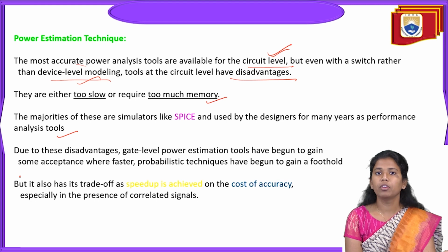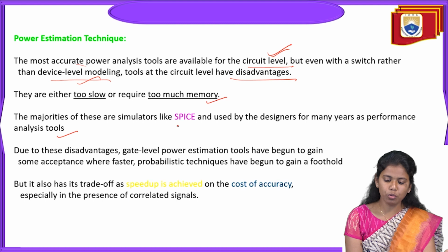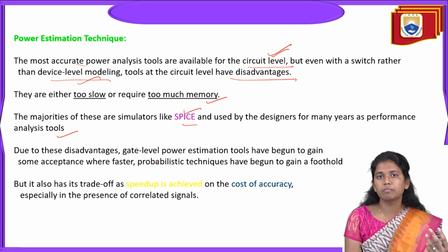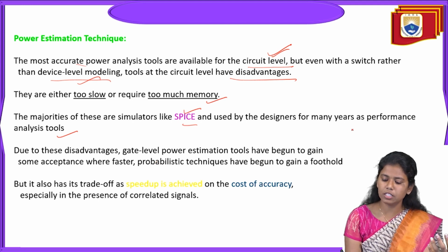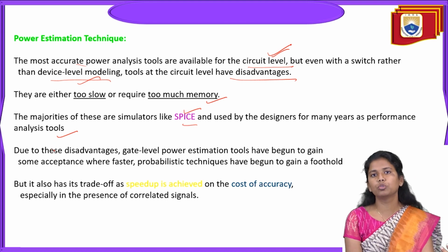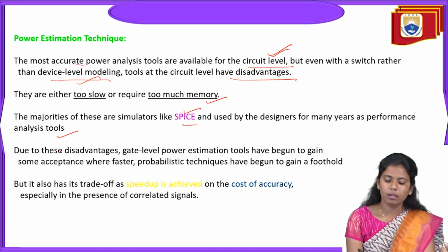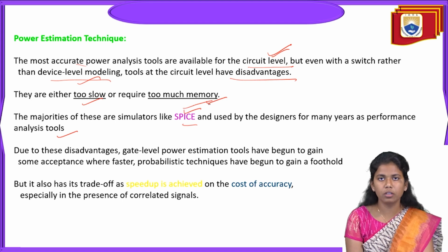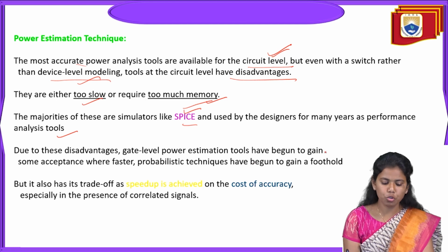We all know that in the VLSI world, we use simulators like SPICE. This simulator helps the designer, and it has been used by designers for many years as a performance analysis tool and as a power estimation tool. But due to its disadvantages, being too slow and consuming too much memory, gate level power estimation tools have begun to gain ground.